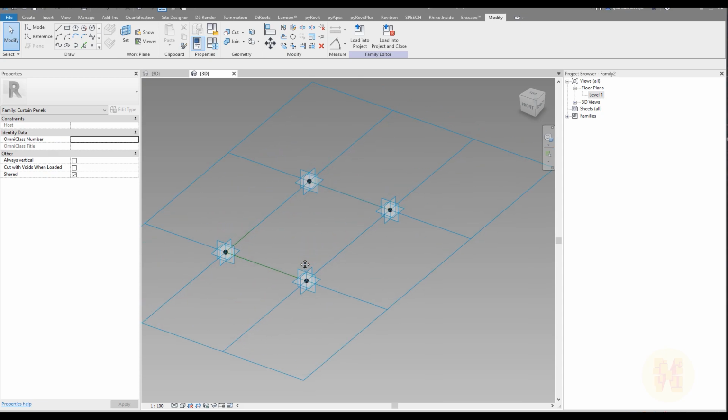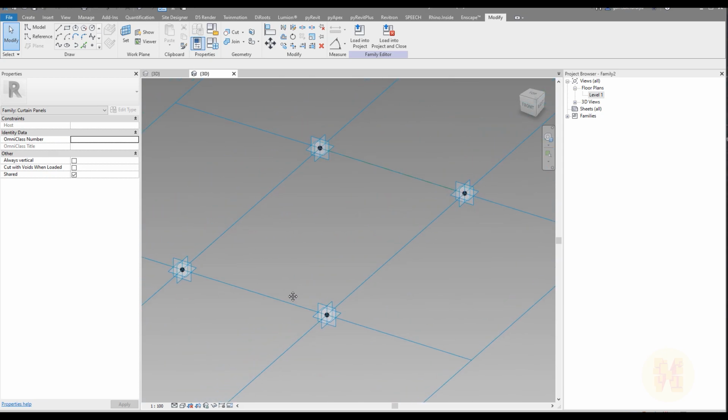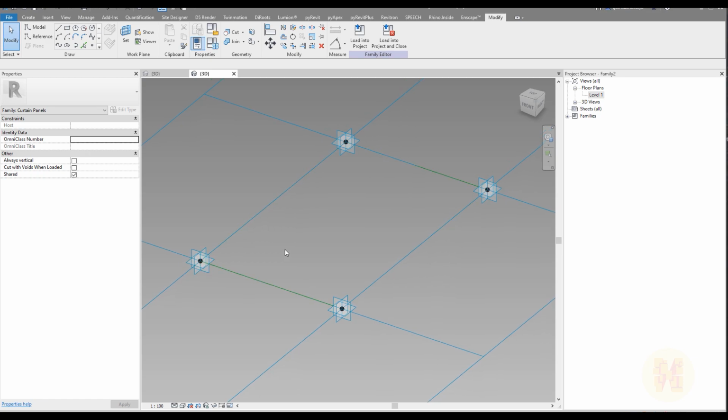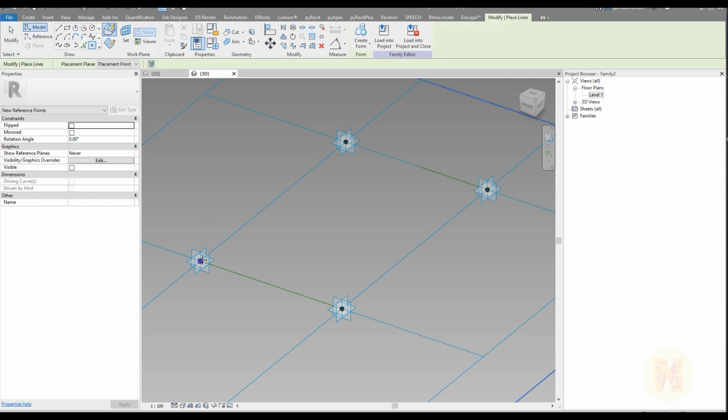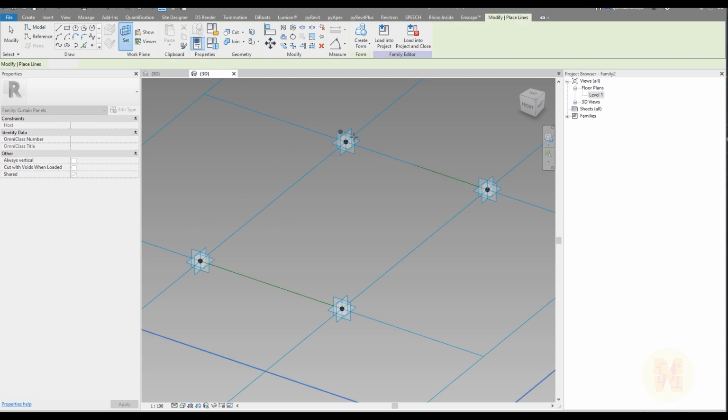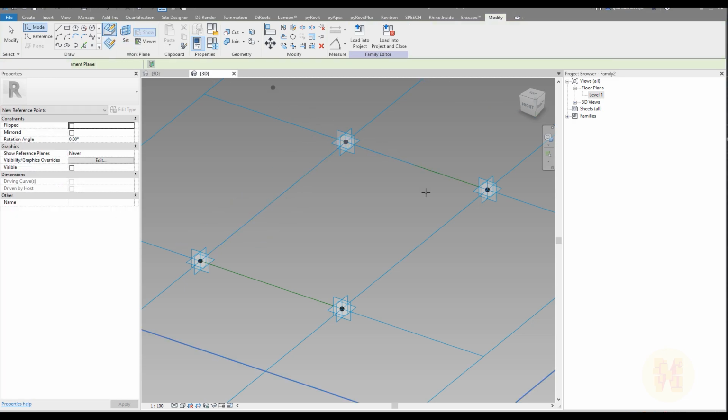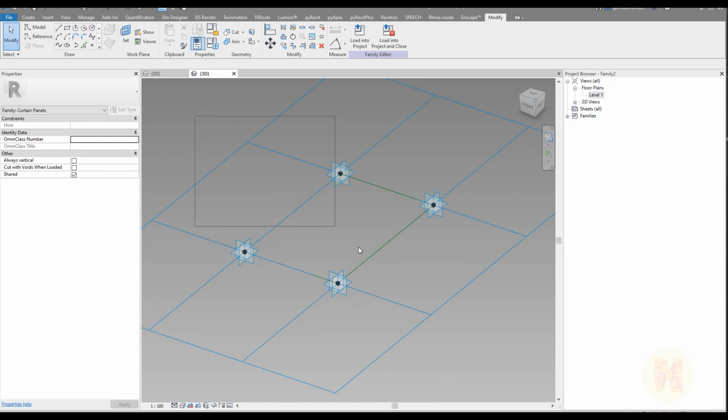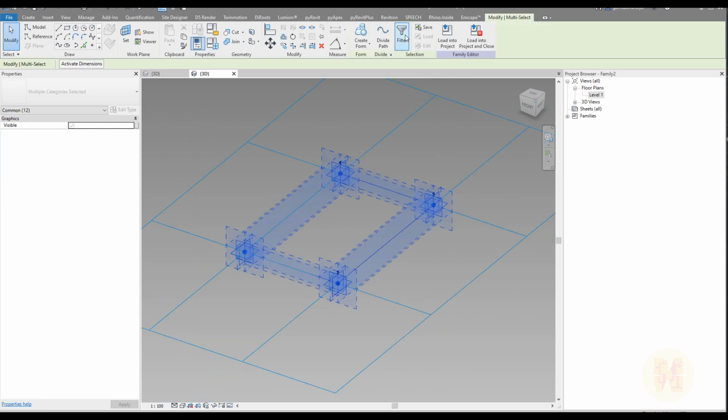We will start to work with 4 points. Yes, today there will be a lot of tutorial about points, so I will create them fast. Set work plane, set your main work plane, and after that select your point element and place it exactly on the point. You should do it several times. Again, set work plane, place the point, and 2 more times, set, place, and set and place. We did it. Now we should select our points. I will select everything because I'm so lazy.